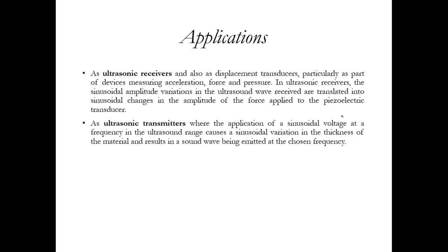Similarly, they can be used as transmitters also, where they act as a kind of actuator, where we apply a sinusoidal voltage of some frequency in the ultrasound range, typically more than 20 kilohertz, which obviously causes sinusoidal variation in the thickness of the material, and it results in a sound wave being emitted at some chosen frequency. So both ultrasonic receivers and ultrasonic transmitters use piezoelectric materials as a basic component.